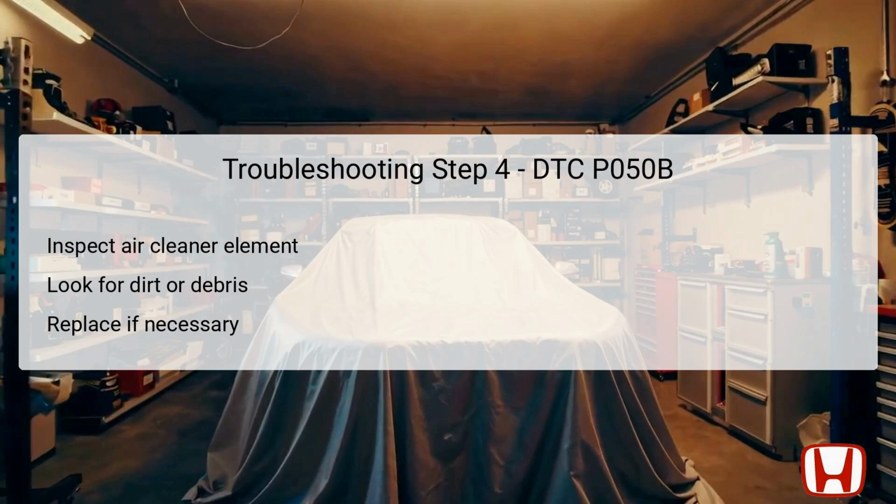It's essential to perform this check regularly, as a clogged filter can severely hinder engine performance. If the air cleaner element is clean, proceed to step 5 for further evaluations. But if dirt is found, replacement is crucial for restoring engine efficiency.